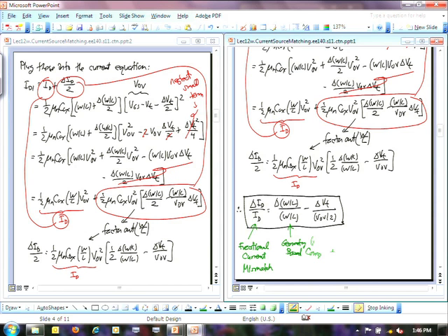Finite bandwidth. Okay, these are all non-idealities in op amps. Stability. And when you put these in a feedback circuit, it's not automatic this is going to work. The stability may be one of the most important things to be able to do when you design and use an op amp. Compensation of op amps. If you find your op amp is unstable in a certain feedback circuit, there is something you can do about it. But you have to understand pole zero diagrams. You should understand to some degree root locus plots.